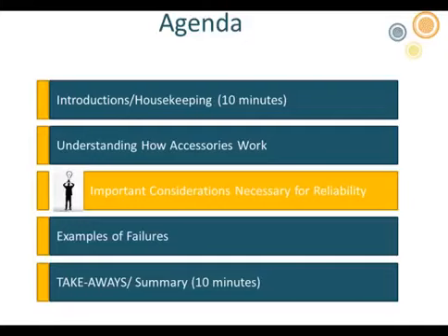And that's another good question, and typically it can show up at your semicon step with terminations that are high dielectric stress control, especially at 35 kV system. You can have as much as 2 to 5 degrees hotter temperature at the semicon step on the surface of the termination than in the rest of the termination.